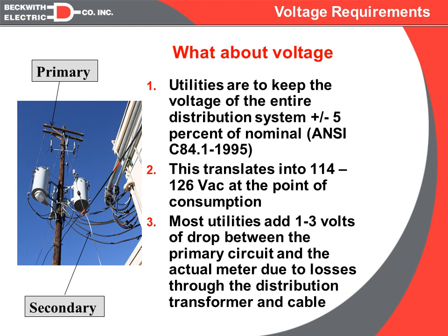Secondary goals are to also reduce the amount of line losses, therefore freeing up more system capacity for real power, and also to attempt to reduce the operations on more expensive equipment and also allow us to regulate the voltage using less expensive equipment from both an installation cost and also a long-term maintenance cost. So those are our primary goals.